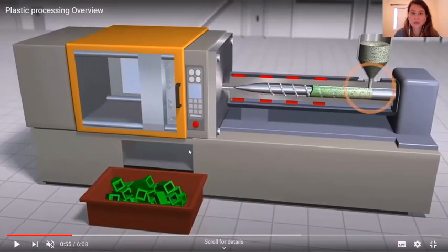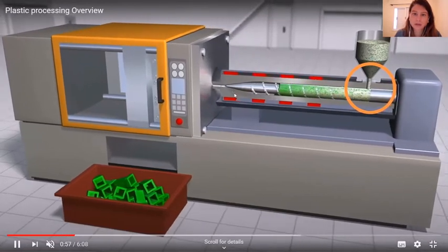So as you can see, the injector has a part that is quite similar to an extruder. So we have a screw, a barrel, and the polymer and additives and so on are fed into the hopper. It falls onto the screw, which rotates, the polymer is melted and pressurized, and the melted polymer is stored at the front of the screw. So as it is represented.